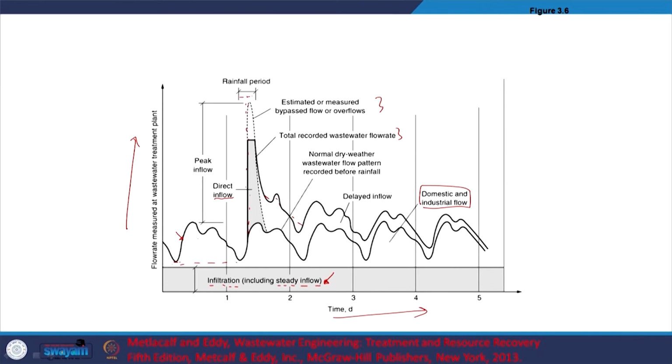So the issue is, do you just design for this particular flow rate, or which flow rate? In this context, people look at peak flow. At least in the US, I believe the design flow rate is the average annual flow rate, but with the rider that the equalization tank will be based on considering the peak factor. I believe we have a figure that will explain this in greater detail.